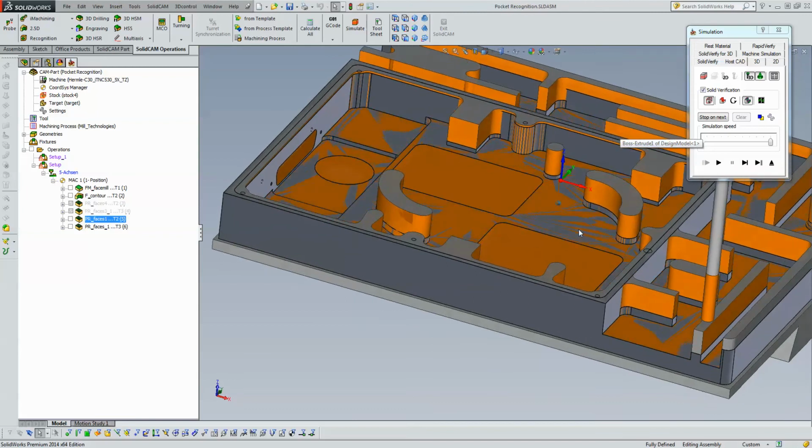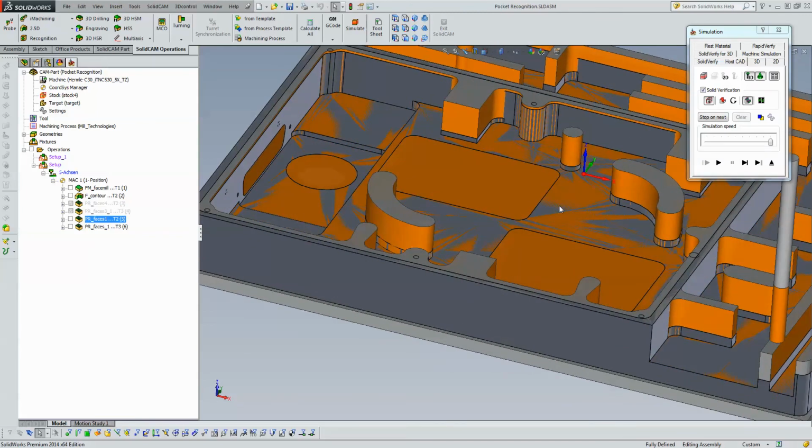This surface that I chose, even though we had a deeper pocket over here, it recognizes that. However, it went directly over to flatten out that area. It recognized that this area was open and just cleared that entire surface over here, whereas these areas, it recognizes them as an island as well.